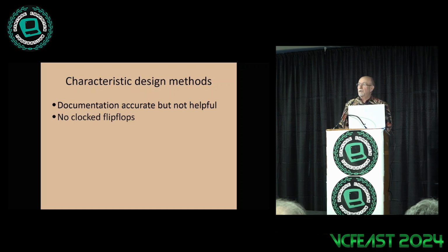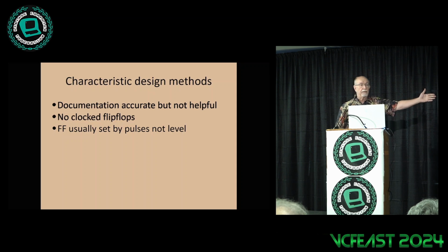This is not really a synchronous machine like you're used to because they don't have any clock flip-flops. So states are just set and reset. Things aren't really happening on a clock edge with a master clock distributed like you think of in any modern system. And that has a lot of repercussions in how you deal with the machine. So those flip-flops are just set by some pulse that comes in. And that pulse might be triggered by something external to the machine that's not even synchronized to the CPU clock at all. It's whenever a disk sector mark happens to come up, pulse comes in, flip-flop changes.